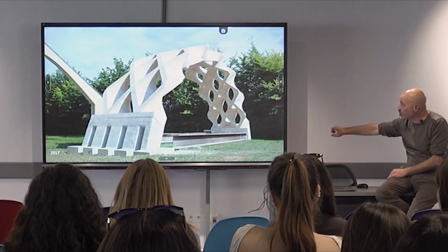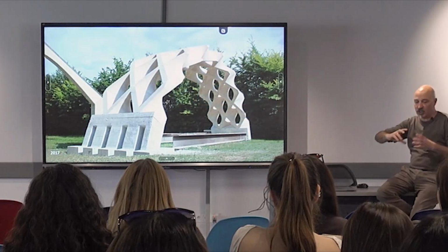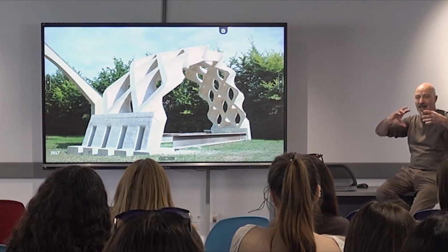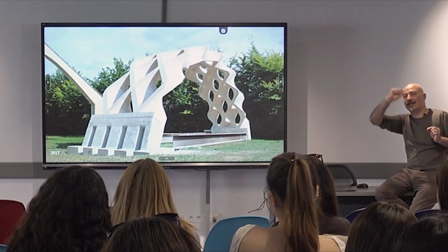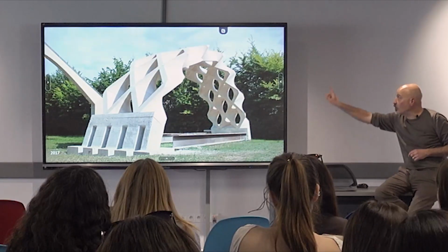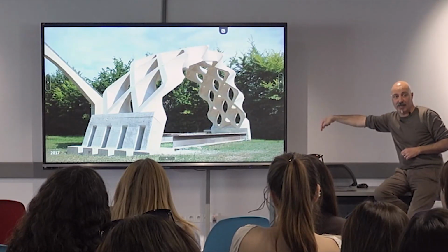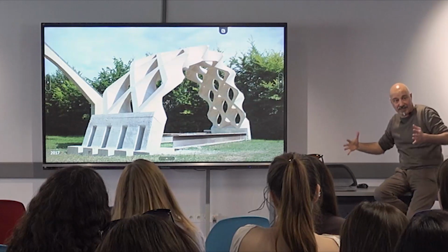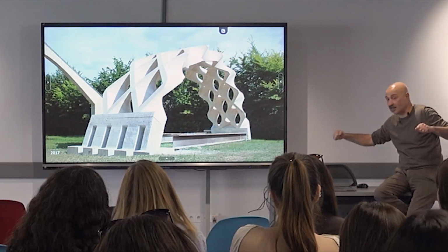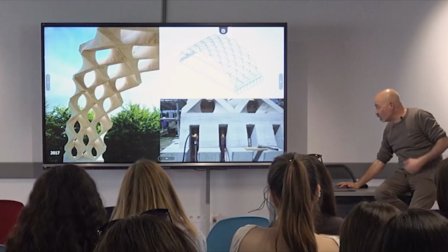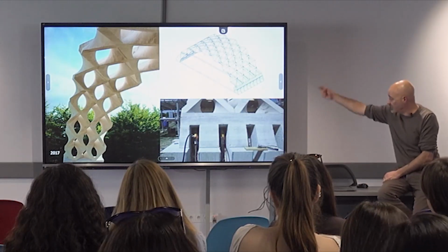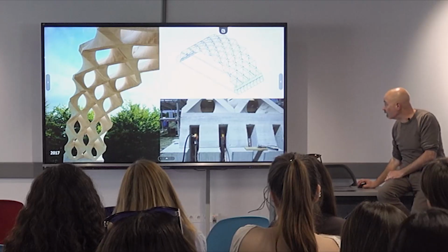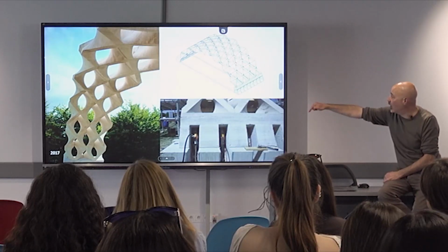And just because each single ashlar is like a torsion block, you have inside one axis in which it's possible to put a safety cable, and you can also pre-stress the system by post-tensioning of the cable. You cannot see it in the exterior, but here you can see the place in which you have the post-tensioning inside the block.